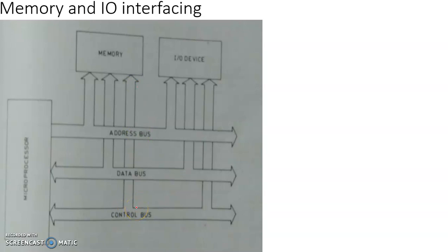We will talk about the control of memory elements and I/O devices as well as the addressing of these devices, how this address is being decoded, in this module. Data communication, that we will talk about in the upcoming module. You can see that the memory is given several lines coming from the address bus. This indicates that generally memory will not be kept as a single chip. Memory will be divided into several chips.